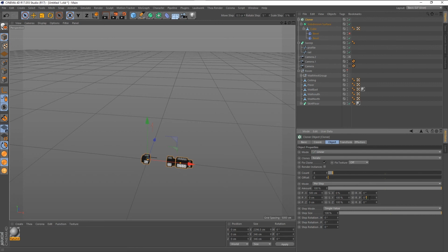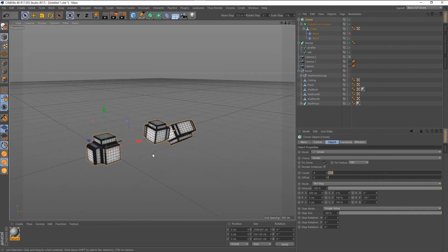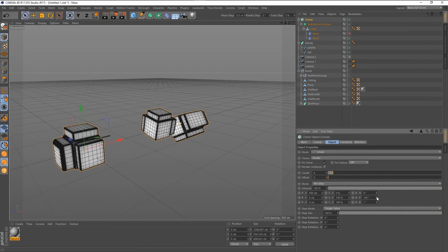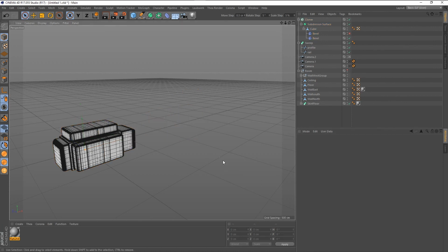So it looks like you can change the pitch. I'm using my scroll wheel to change that, but we can hold the Shift key down, and that changes the pitch of the rotation. So feel free to play with that. You can see that's interesting. And that's how you array objects, and that's how you use instances.